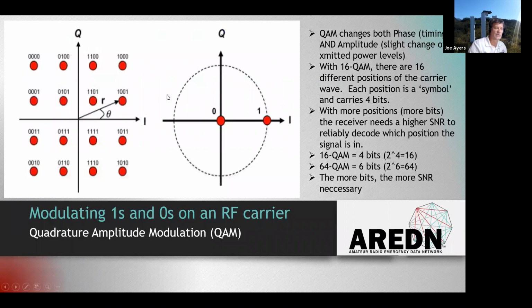So I'm just showing here that I and Q mathematical representation, but it's still a carrier wave. And this is the quadrature amplitude modulation scheme of modulating information. Well, we're now going to hold that signal into 16 different discrete states, and we call this representation 16 QAM, and with that we're transmitting 4 bits for each position of the signal.